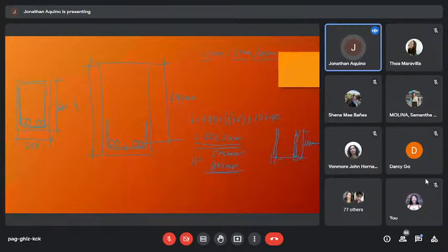So although in design, theoretically, i-design natin siya as steel reinforced, but the code requirement and in practice, we are providing at least 2 bars on the top. So the purpose of this is to hold the stirrups, okay?